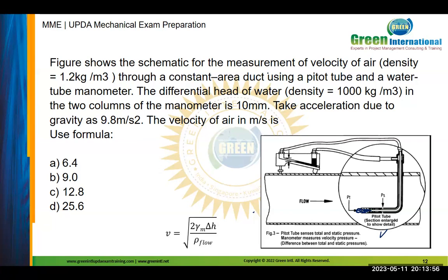So what else? During the movement, some of the flow goes inside through the holes and travels through the annulus between the outer tube and the inner tube, and measures what? This reflects static pressure. Why? Because there is no stagnation for the flow.